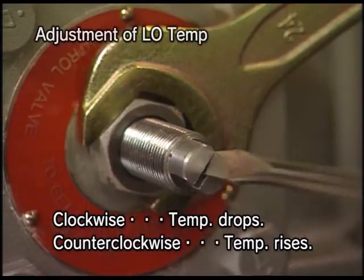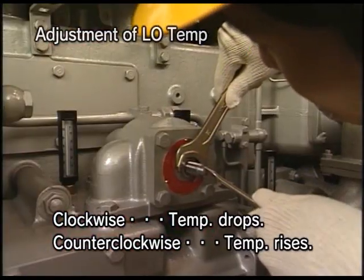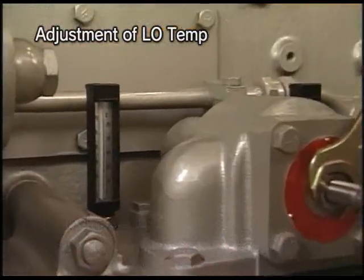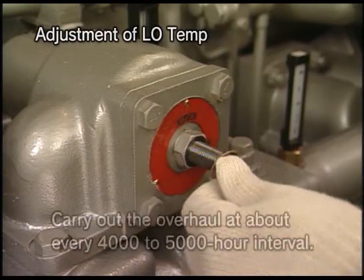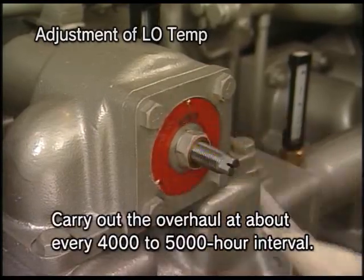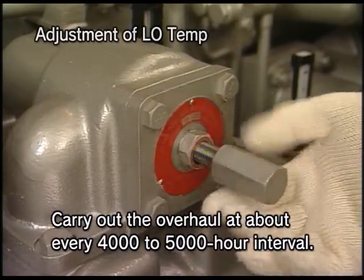After the check, loosen the lock nut, turn the adjusting bolt, and adjust the temperature. After the adjustment, tighten the lock nut, fit the cap nut, and the work will be completed.